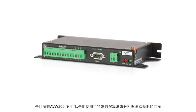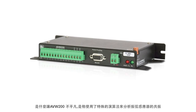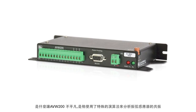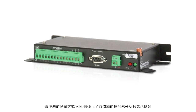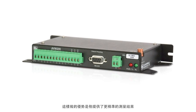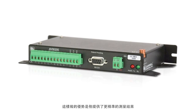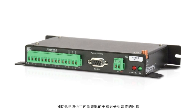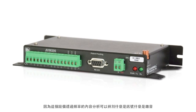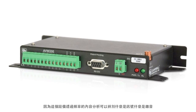applications. What makes the AVW200 unique is that it employs a spectral analysis algorithm to measure the resonant frequency of the gauge. This is different than the traditional methods of measuring vibrating wire gauges, which use a time domain method. The benefit of doing this is that it provides excellent precision, which is orders of magnitude better than the time domain method. Another benefit is that it is more robust to the influence of external noise, because the device is able to discriminate between signal and noise based on the frequency content of the signal.